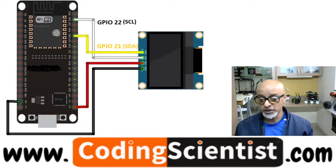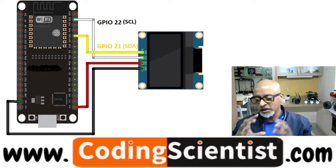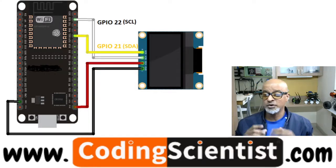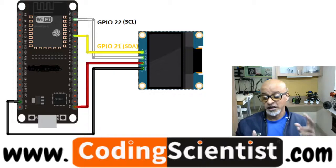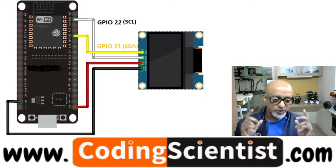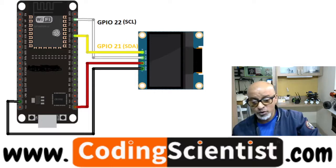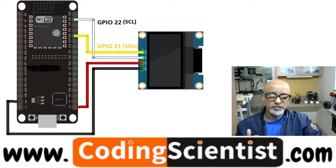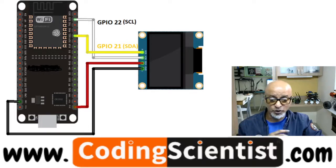I will show you how to install it, and there is also a tricky configuration in that particular library. By just installing the library, you may not be able to drive the OLED using ESP32 or even Arduino, right? There are a few tricks, a few modifications that need to be done in the library. I am going to show you how. We will use the existing sample code which comes along when we install the SSD1306 library and upload that into the ESP32 board.